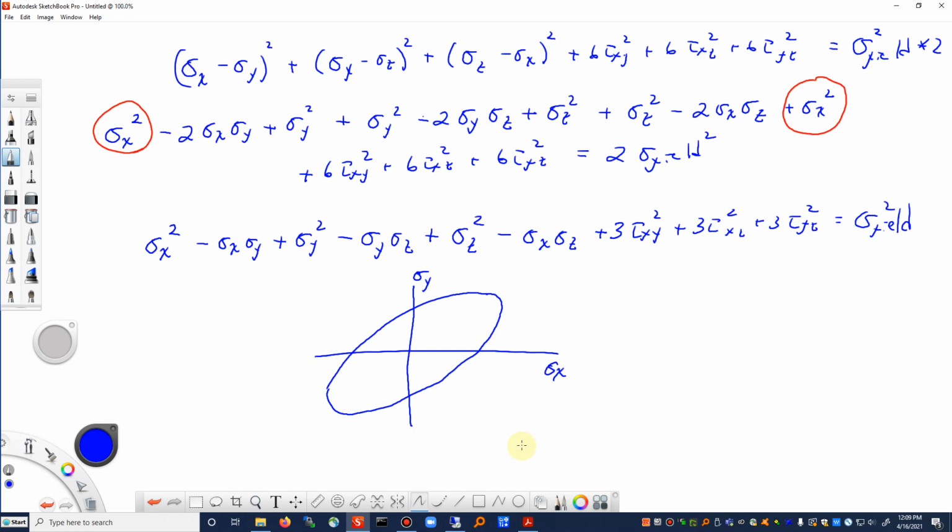So in 2 dimensions, we have an ellipse. In 3 dimensions or higher, we have an ellipsoid. Higher than 3D, some people call that a hyperellipsoid. But in any event, if we were to plot one plane, then it would look something like this. And what this envelope represents is based on whatever number that is for the yield stress. If you have a material that's stronger, then this ellipse is bigger. If you have a material that yields at a lower stress, then this ellipse gets smaller. But it stays the same functional shape.